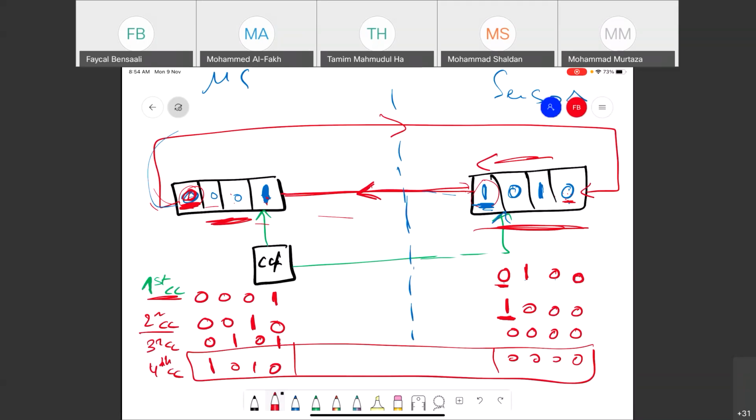Some sensors provide more than one value. So it has more than, let's say, one shift register. So you need to select which shift register you need to read from. And for this type of device, the master first sends a command or the register number: I want data first from this register. So it will tell the device from which register it needs to read, and then it reads the data. Do you get my point?